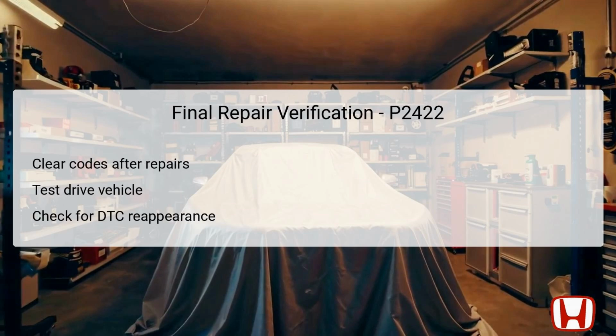Upon completing the necessary repairs associated with DTC P2422, it is imperative to conduct a final verification of the repairs made. Start by clearing all DTCs with the HDS to reset the vehicle's diagnostic system. It's crucial to perform a test drive under varied conditions, invoking different engine loads, speeds, and environmental factors to confirm the effectiveness of the repair.